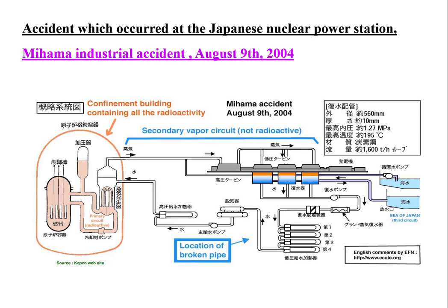Although this thinning started from the early life, and it took 23 years to come down to that very low thickness, because they actually did a wrong inspection. The organization which runs and maintains this station did not inform that this type of pipeline has to be inspected using an ultrasonic inspection technique.